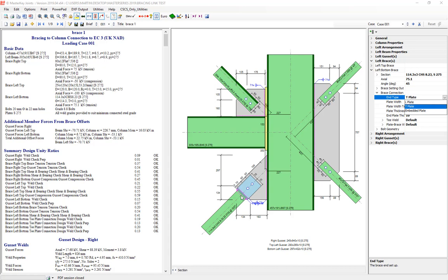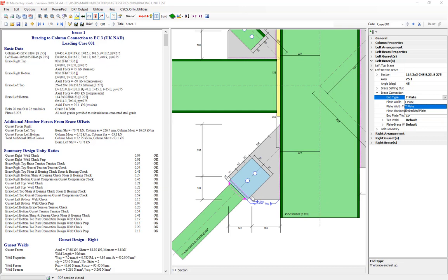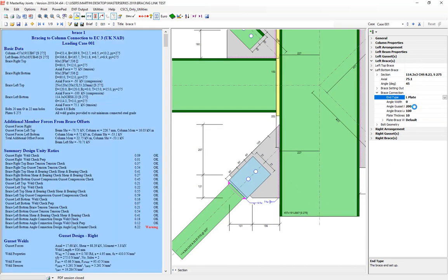So the T plate basically is an end plate welded to the section, and then centered on that we have another plate coming out from it, forming a T, and from which all the design of the welds and everything are calculated. If you go for an L-shaped section, you have to specify the size of the angle L that's being provided here instead of a T.